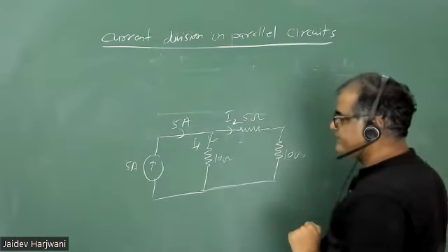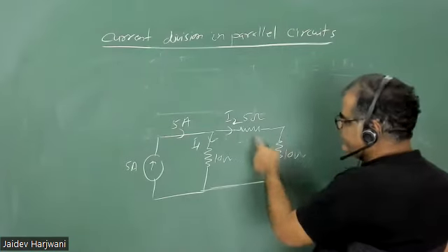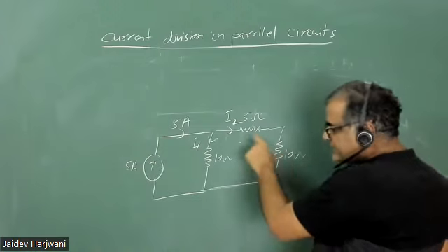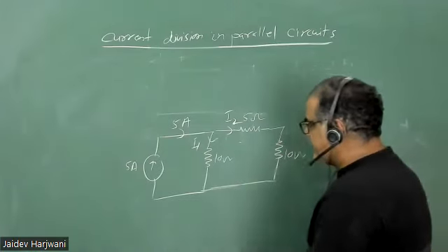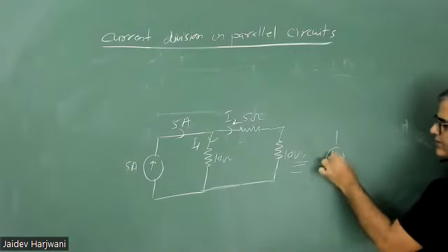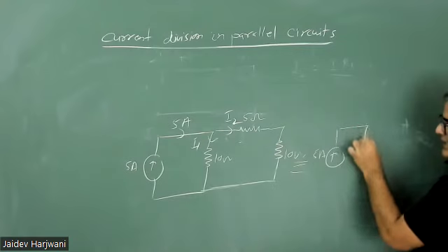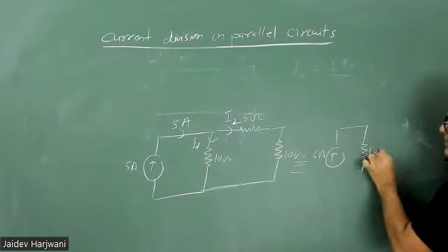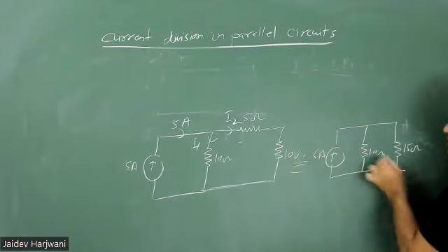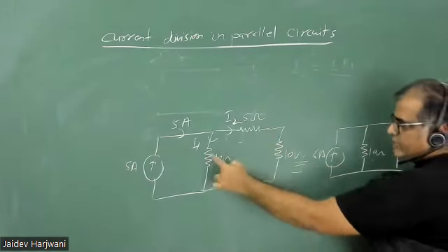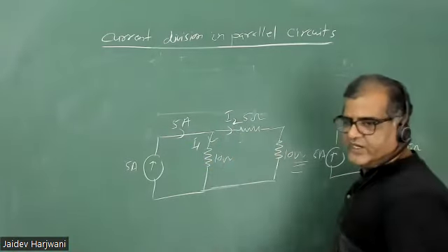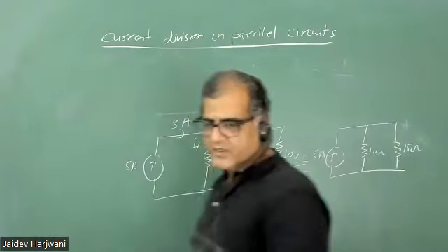Are you getting this? Whether I write 25 here or 5 and 10 distributed, that is the same thing. The resistance is the same. I can again put an equivalent resistance of this one, 5 amp, and this is my 10 ohm, and I can put this now as 15 ohm. This is the same thing. They are in series. The same current is flowing in the resistors; when the same current is flowing, that means they are in series.